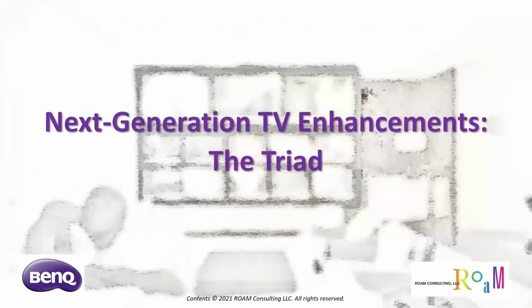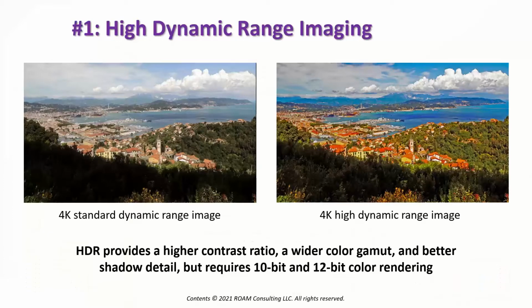So, enhancements: what really makes Ultra HD different from Full HD, not just more pixels. The one that is the most obvious, you see it right away, is high dynamic range imaging. What that means is that we're able to capture more shades of light and more shades of color over a wider range. So we can see much brighter highlights, much deeper shadows, and much more saturated colors. But it requires 10-bit and 12-bit color rendering to make it happen.